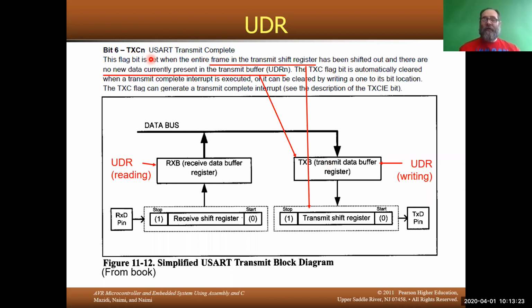You're going to set it such that an interrupt doesn't occur all the time now, because otherwise you'll be just transmitting nothing, and that's not what you want to do. So when this flag is set, and it can be tied to an interrupt, you want to stop this interrupt from occurring each time a character is done. I've got code that we're going to look at probably Friday showing exactly how to do that.